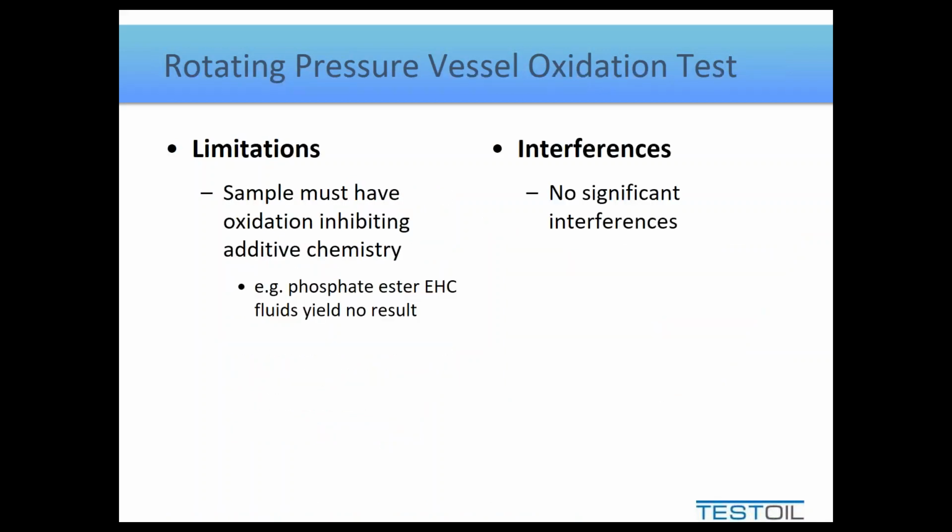Now, the limitation with this test is the only oils we can test have to have an antioxidant or oxidation inhibiting additive chemistry, which means fluids like phosphate esters typically cannot be tested. As for interferences, it doesn't really have any that cause any significant change here. So that's the good part.